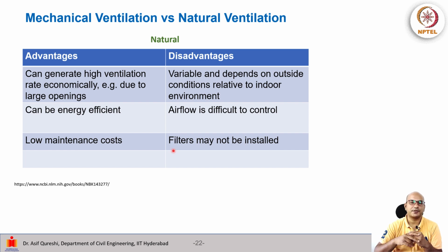It may not be possible to install a filter, because once you install a filter, we are providing an obstruction to the flow, so the flow rate will reduce. In mechanical ventilation it was okay because the fan will move and push the air anyway. In natural ventilation it's a natural barrier, so the airflow will reduce. So filter installation is a bit tricky.